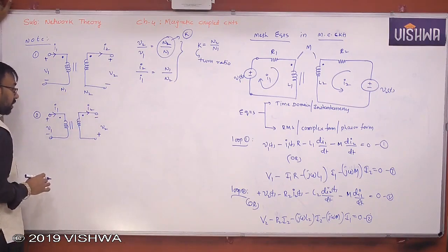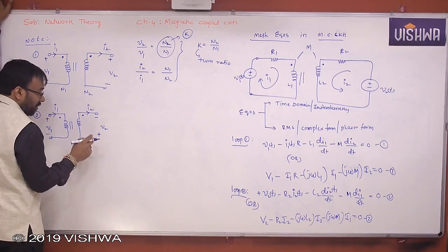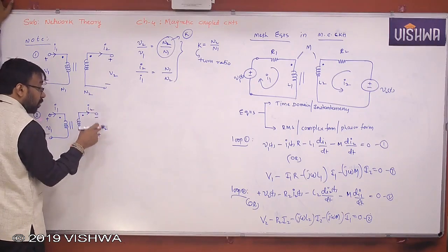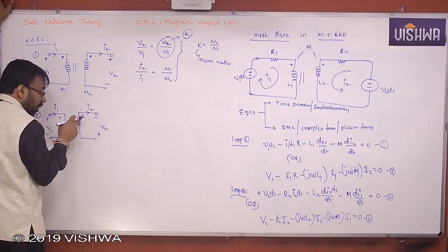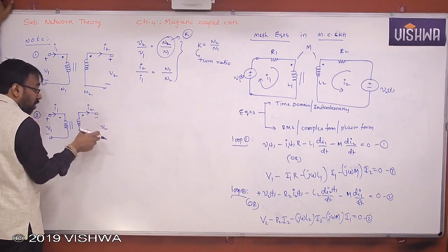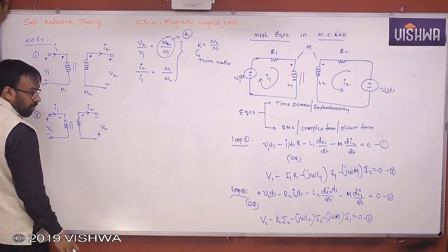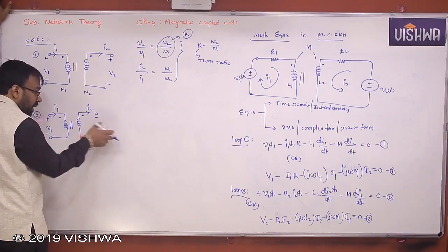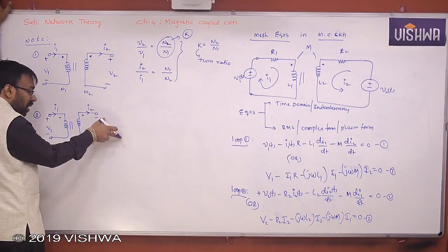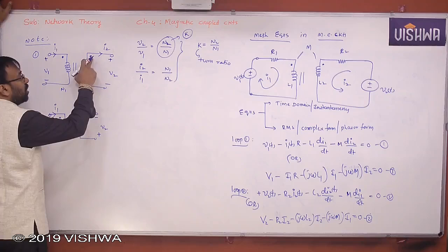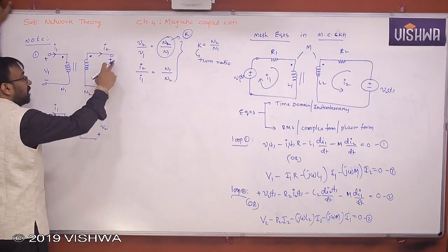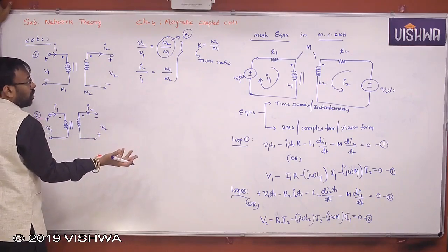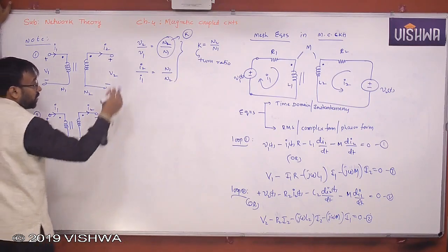Well, but what is actually happening here is the polarities of the voltage across these two terminals is supposed to be plus minus because of the higher potential. But you are measuring the voltage with minus plus. See, the actual voltage polarity is plus minus. But the desired polarities are what? Minus plus. The actual polarity is what? Plus minus. The desired polarity, that means you are connecting the voltmeter with plus minus only. Therefore, there is no problem. Understand all of you? Okay. That is why you got plus only.